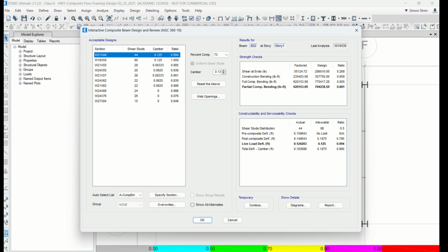Now let's look at it. Strength check, you have to do it for safety. Serviceability check for deflection, right? So this is to check the backup calculation. So this member, see what we see based upon all the load combinations. There is a factored load. This one is pound per foot. So it's 620 kip-feet, right? This is the design moment for the permanent condition. Okay, go back to here.